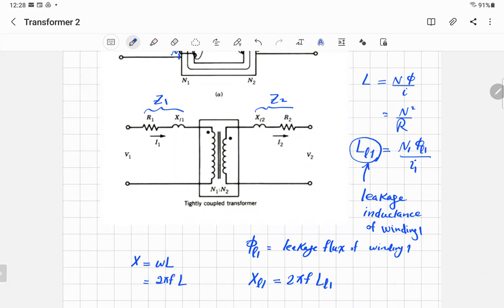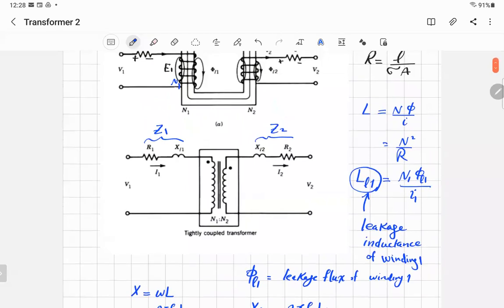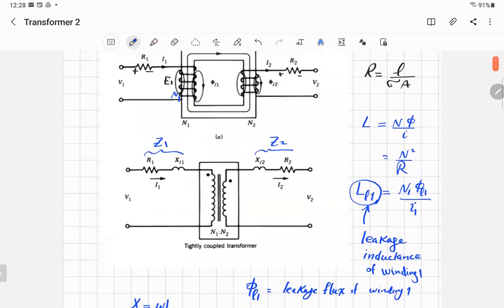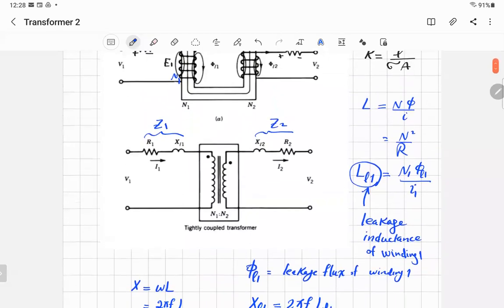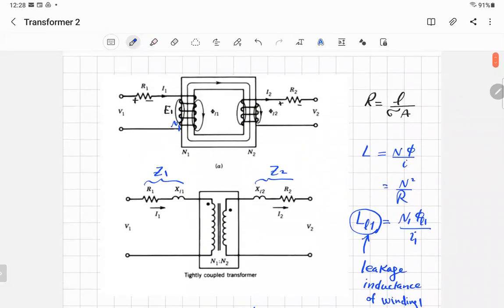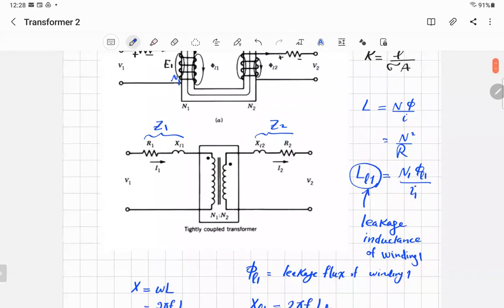There is something else. We talked about the voltage drop due to the resistance of the winding and the flux leakage, and that leakage here is not connecting both. What about phi m? How can I represent it? There are two phenomena that we didn't include yet in our practical transformer model. The first one, phi m, is the mutual flux flowing through the core, and that's responsible for building the magnetization in the transformer.